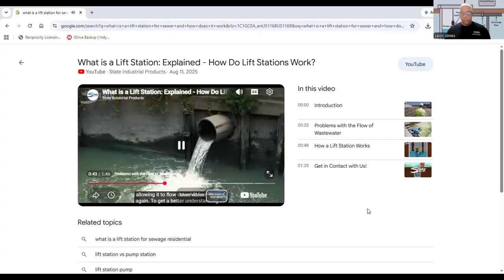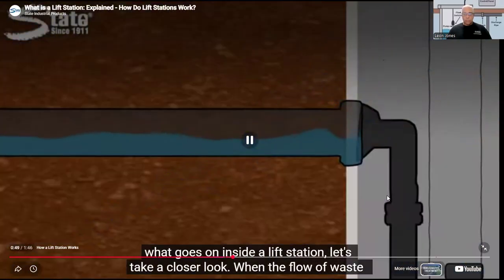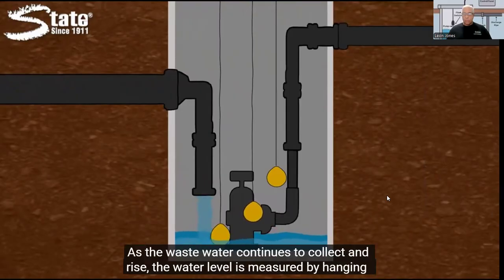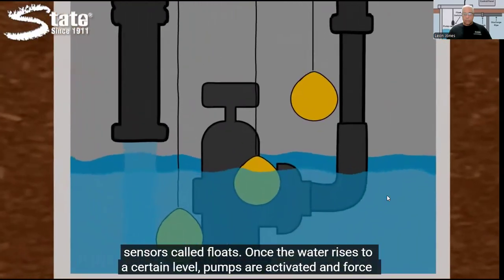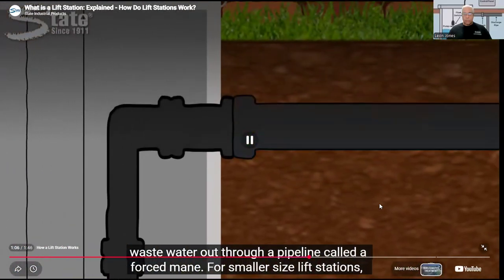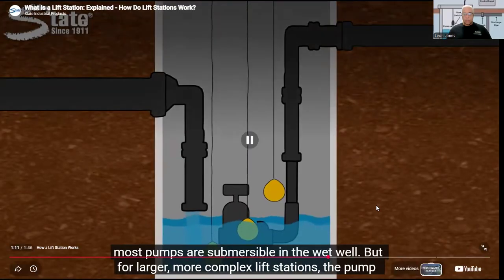To get a better understanding of what goes on inside a lift station, let's take a closer look. When the flow of wastewater enters a lift station, it collects in the underground tank called a wet well. As the wastewater continues to collect and rise, the water level is measured by hanging sensors called floats. Once the water rises to a certain level, pumps are activated and force wastewater out through a pipeline called a forced main.